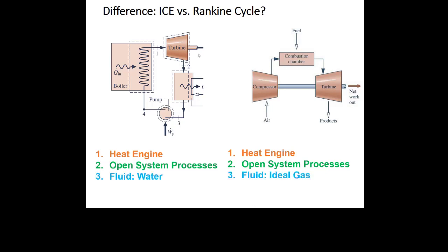The difference between a Brayton cycle and a Rankine cycle comes when we ask the question, what's the fluid? Because with a Rankine cycle, what's the fluid? The answer was water, right? So we were thinking, okay, now what's the phase? Is it an ideal pump? But now, in a Brayton cycle, the working fluid is air, which we're going to treat as an ideal gas. So now I'm going to say, well, where's the isentropic processes? Now, unlike the internal combustion engine, we're not going to assume that everything is always ideal, right?